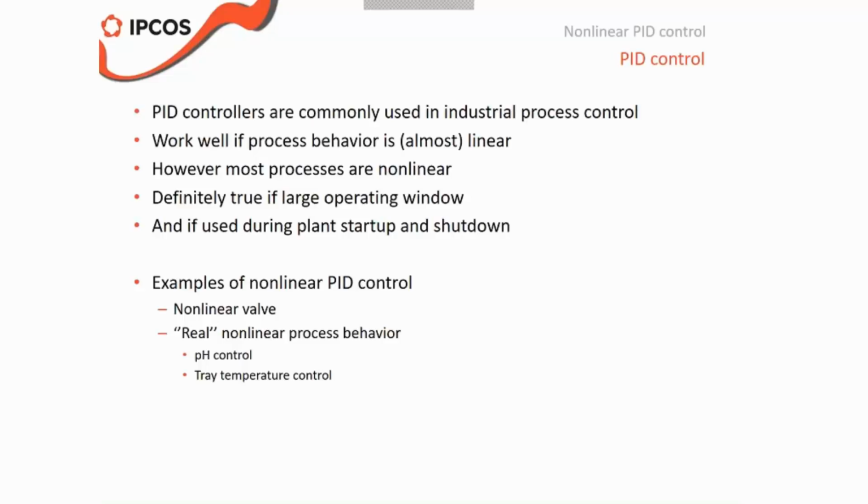In some cases they struggle a bit, and if I look at process behavior, then when do PID controllers struggle? It's mainly when processes are very slow or when there is a large dead time. If you have something like that, then typically you might want to use an APC controller, which has a much higher performance compared to PID controllers.